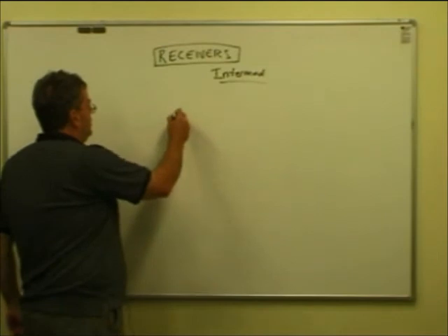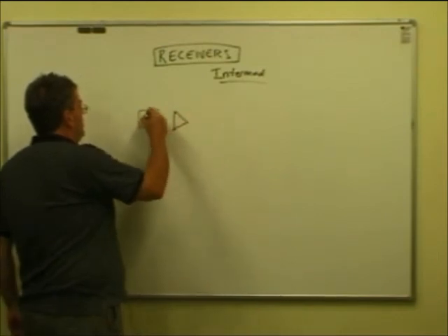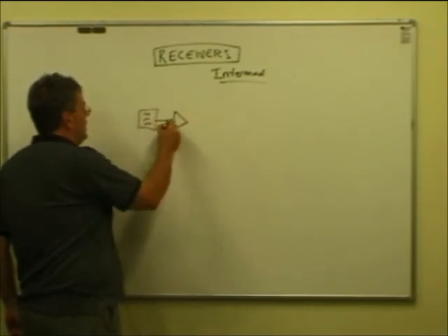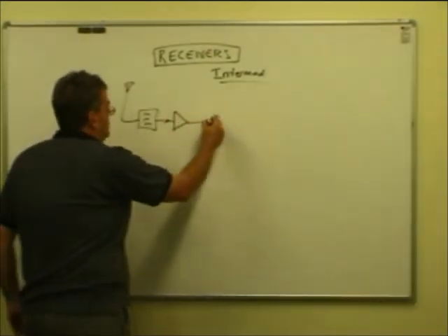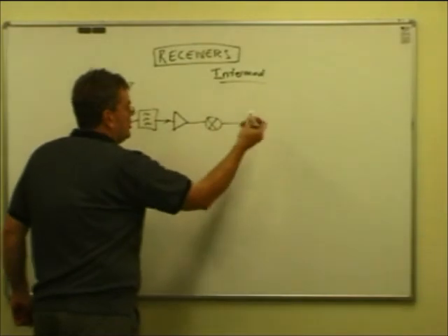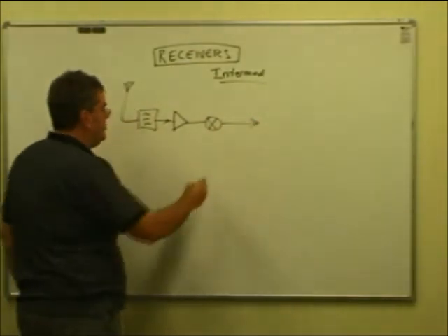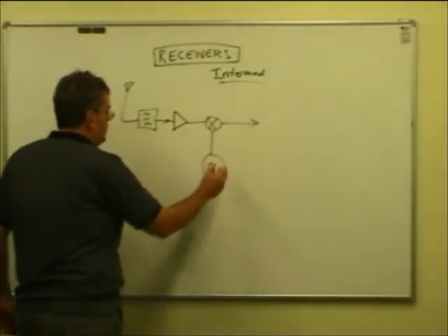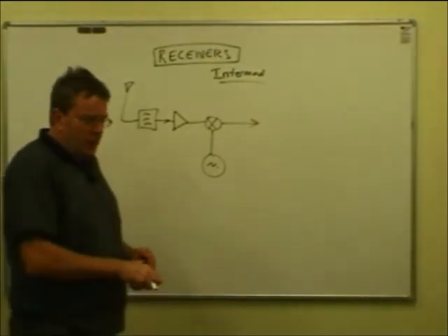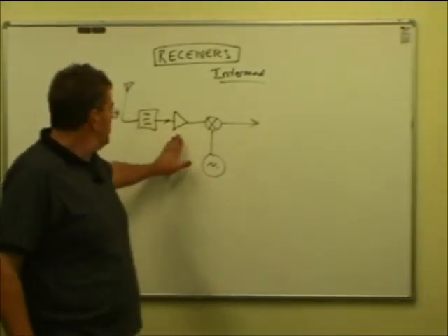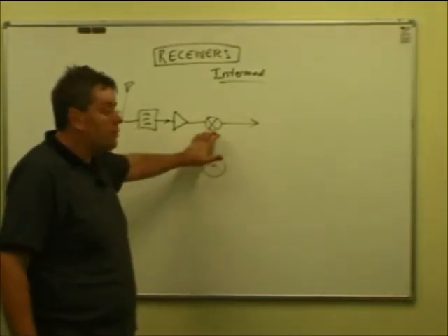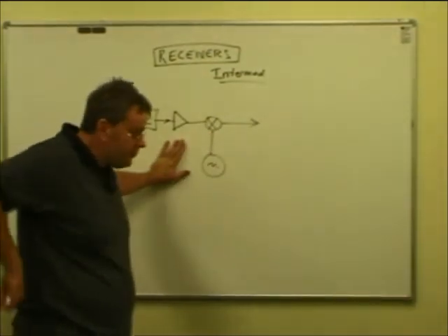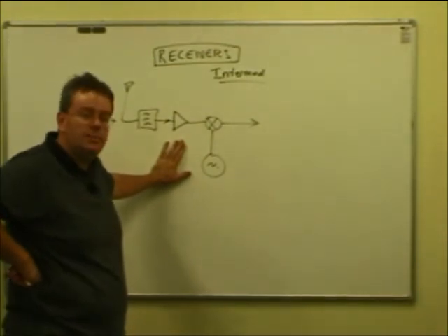Remember, we've got a bandpass filter, just allowing the amateur band of interest to pass through, then an amplifier, then the mixer, which is fed from the local oscillator. These amplifiers aren't perfect, they add a bit of noise. The mixer adds a bit of noise too, and signals can combine in them in other ways as well and create new signals.